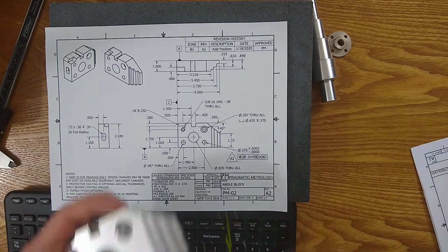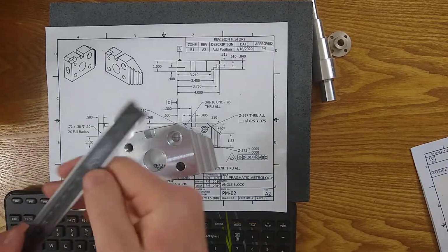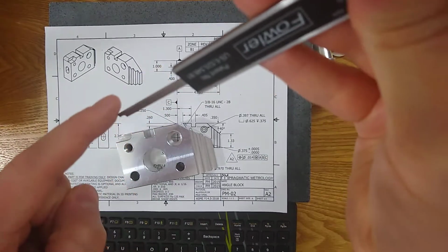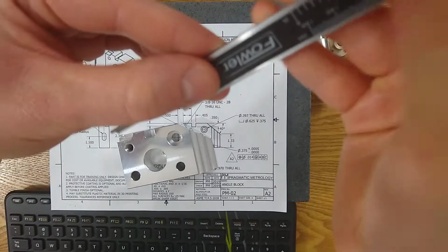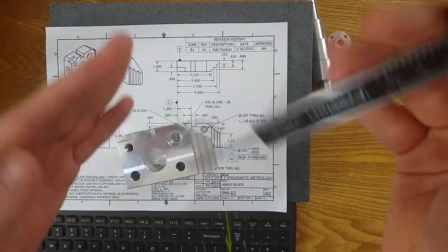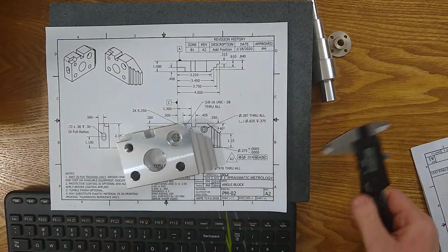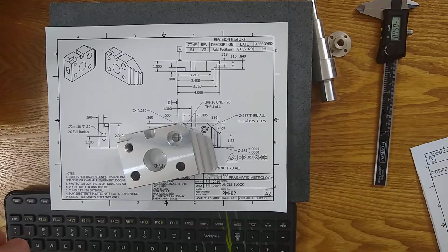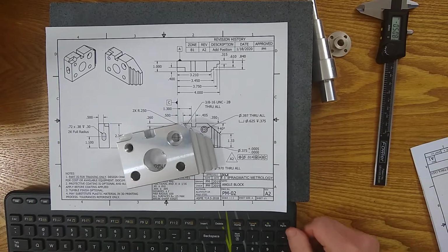Now, if you drop a caliper depth bar into a hole, if you grab it down on the side, you will get a shallow number, and then as you go deeper into the tip, you'll get a deeper number. So you get two numbers. What we care about is the full diameter. So a pin gauge is going to check the full diameter. And then watch for walking.